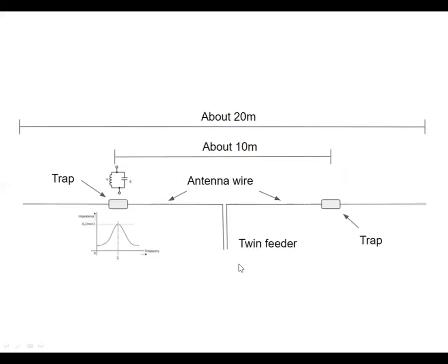The way it does it is, if you look at the drawing of what it is, we've got our feed line here, the coax, and then we split into two elements. On an element, we've got this length, which is about the length of a 20-meter dipole. And then we put an LC circuit in here, which is a reactive circuit that we can design with different capacitances and inductances to make it very high impedance at the lower frequencies, at 20 meters.